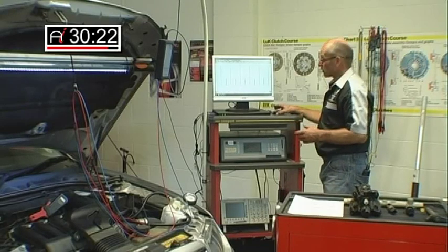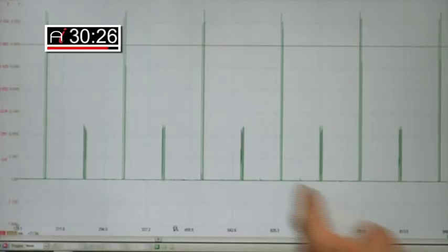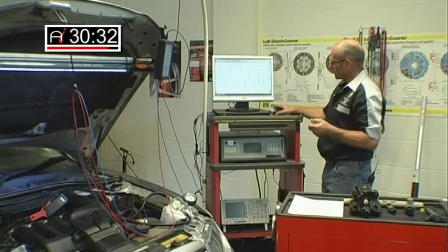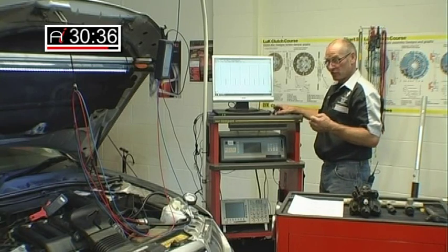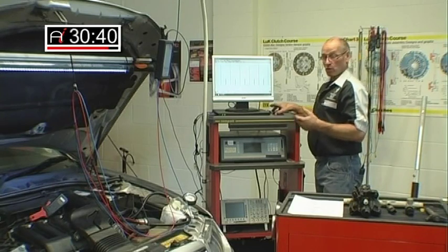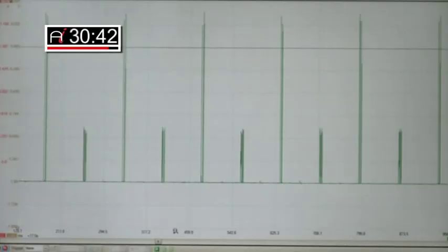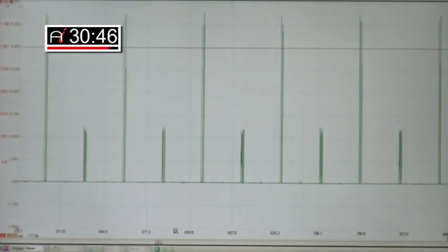These injectors work on the principle of two events, pilot and main, which I'm going to zoom into in a moment. And this event here is an extra event which takes place to top up the capacitor in order that that capacitor is charged sufficiently to open the next injector event. Which is why, if one injector were to fail, that won't happen, therefore the next injector opening event will not happen.